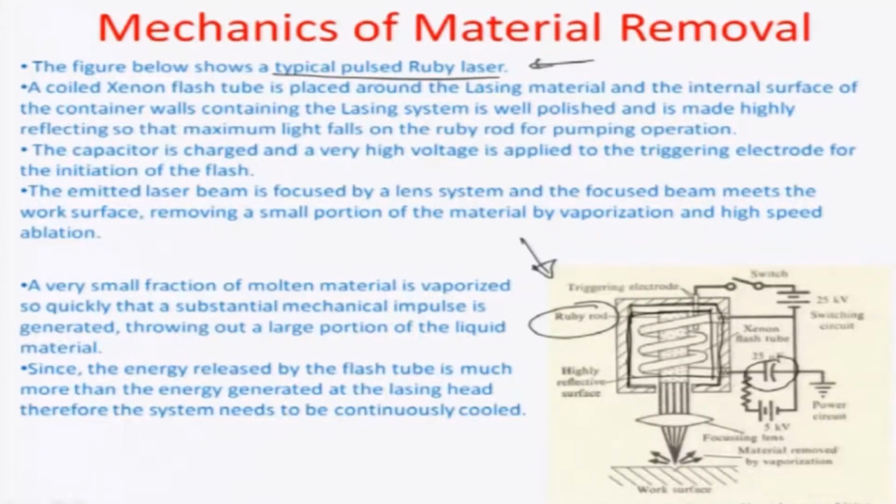The emitted laser beam is then focused, and there is of course this whole principle of amplification and emission happening, and there is occasionally a loss of photons. Most of the photons are retained within the medium for amplification, but the occasional loss of photons forms the cutting beam, which comes out of the optical system, hits this lens right about here, and then gets focused very narrowly onto a small spot near the workpiece. So, you have to focus a laser system very closely with respect to the workpiece before you start the melting and vaporization process.